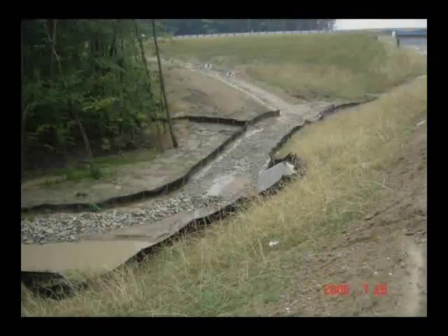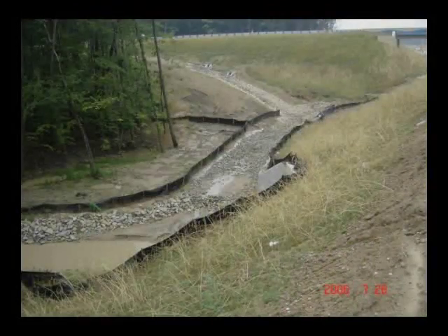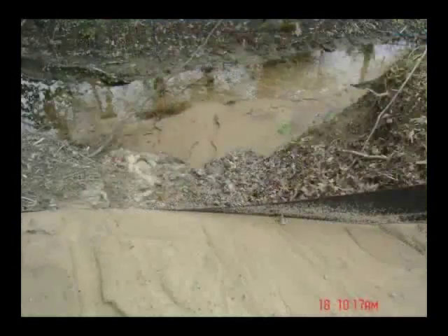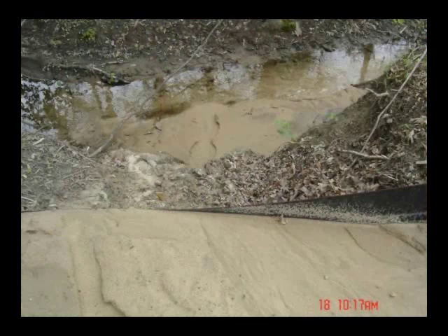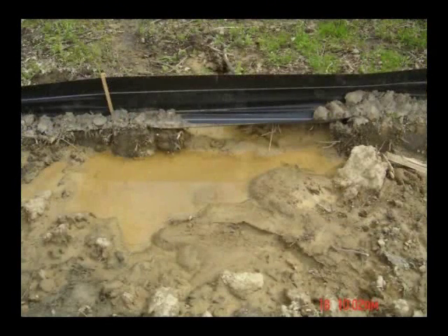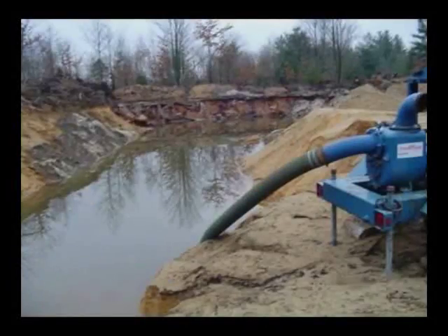A large construction site may have several hundred yards of silt barrier. It is important when doing inspections to accurately record the location of any problems. Ensure that sediment accumulations are not excessive, that filter materials and stakes are in good condition, and that silt fence remains properly trenched in. Dewatering is the removal of groundwater, surface water, or stormwater from a site to allow construction to be done in dry conditions.